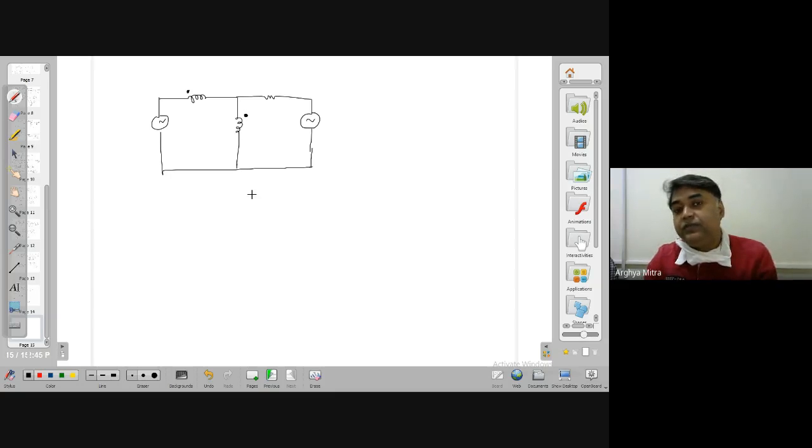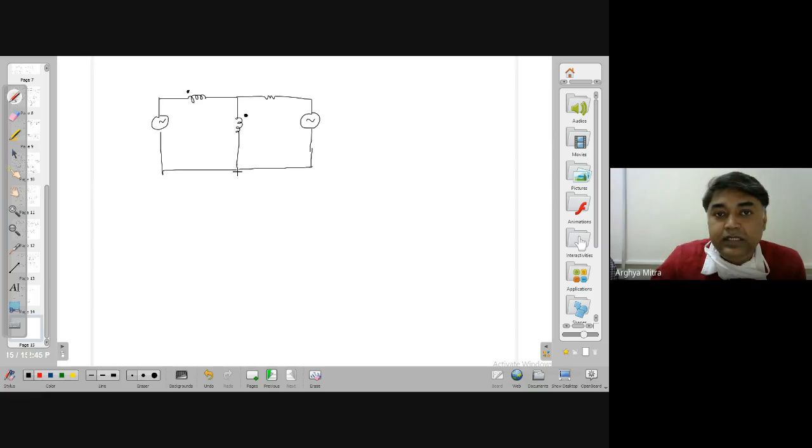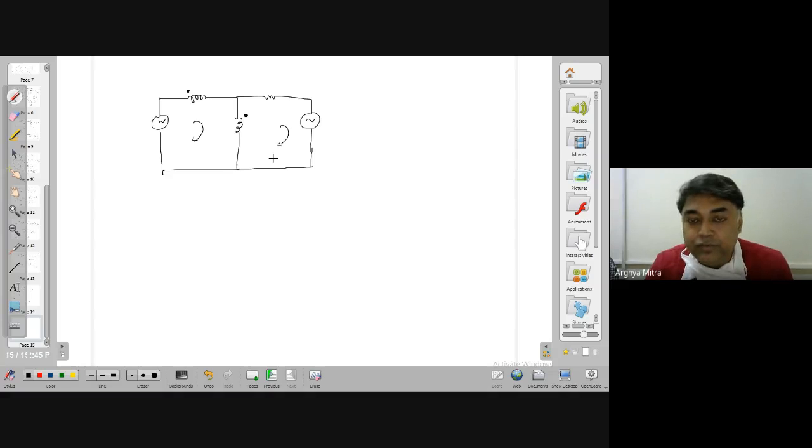Okay, I have some dot representation. So if I place it in this fashion, then how can I solve for the currents? Let it be in the frequency domain, but you need to create the circuit first with these coupled inductor cases, because you know that when there is a coupled inductor, then an induced voltage will be created in the branch because of the current in the other inductance, isn't it?